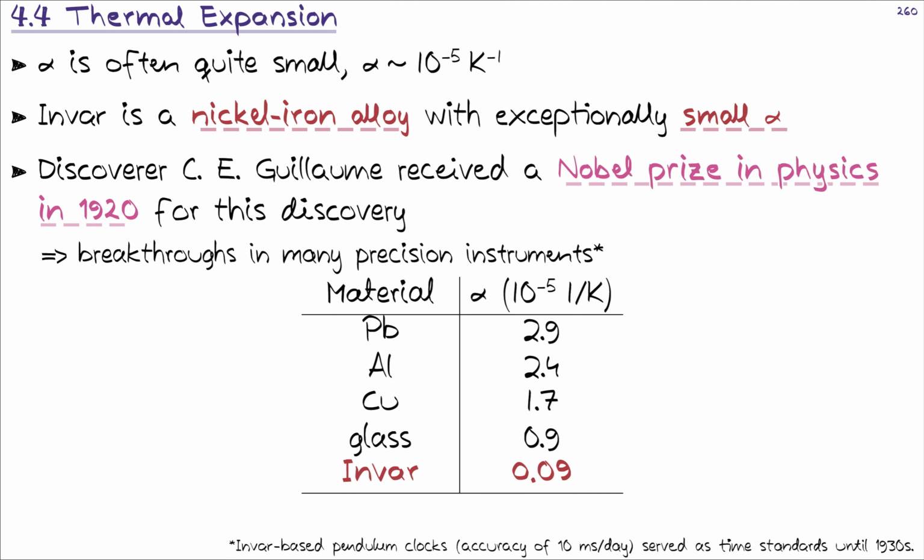And if I recall correctly, you can even purify INVAR further so that you can make even better materials based on that. And I think INVAR is still being used in applications where, for example, you need a material that works at very different temperature ranges. Especially in cryogenic applications, I believe INVAR is still a material that is being used quite a bit due to its thermal properties.